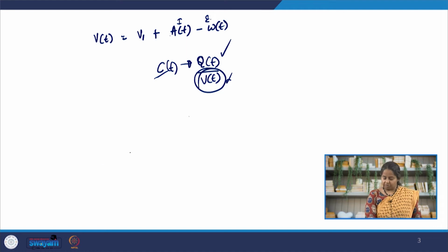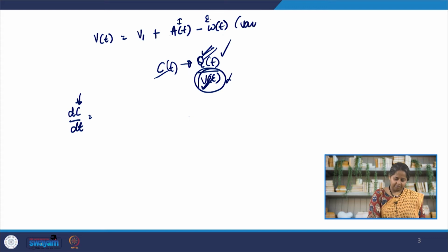So, very briefly, I want to start with something very simple, dC by dt. When we do a mass balance, we are very interested in dC by dt. Here, C depends on both the flow rate of the contaminant that we are interested in, whether it is a kind of bacteria or a kind of antimicrobial, and the volume of the tank, which is variable, it's not constant. Remember I told you that when we talk about dm by dt, you need to account for both C and V, especially when V is not constant. We are going to do that here.